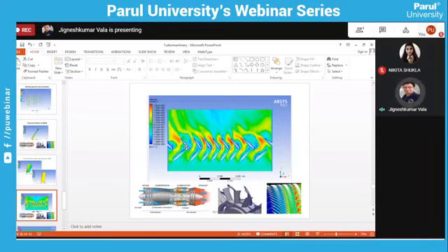If we observe the first stage, fifth stage and tenth stage of the blade, we observe that in the first stage the turbulence is generated near the trailing edge, and at the fifth blade the turbulence is not generated near the trailing edge. But after covering some distance, it reaches the maximum value of velocity.